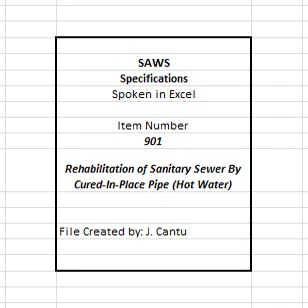3. For each CIPP liner section installed, the contractor shall obtain CIPP samples large enough to provide a minimum of 3 specimens and a recommended 5 specimens for flexural testing. CIPP samples shall be prepared and physical properties tested in accordance with ASTM F1216 or ASTM F1743, Section 8, using either method proposed. The properties must meet or exceed the values listed in Section 901.2.3.d. If test results do not meet the properties, contractor shall remove and replace CIPP at no cost to SAWS.